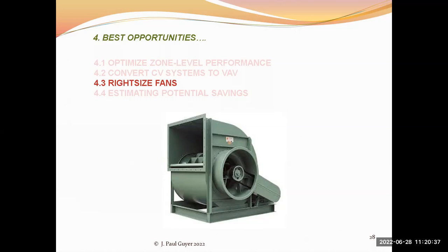Now, in diagnosing the oversized fans in constant volume systems, if it is not economically feasible to retrofit to a VAV system, to convert the constant volume system to a VAV system, resizing the constant volume system is generally a profitable choice.